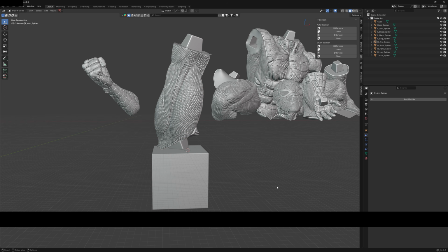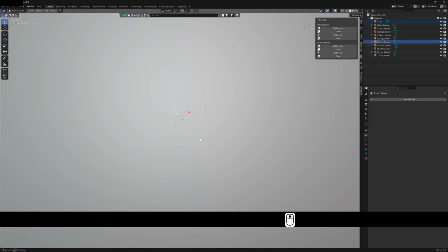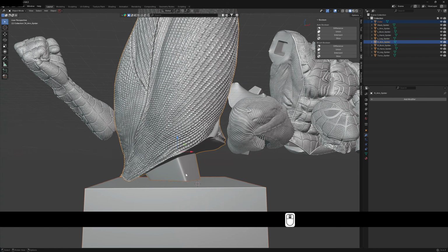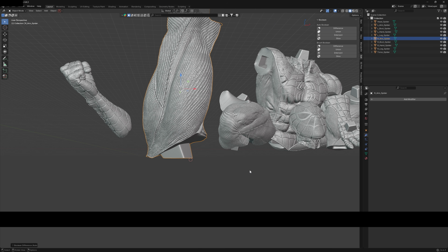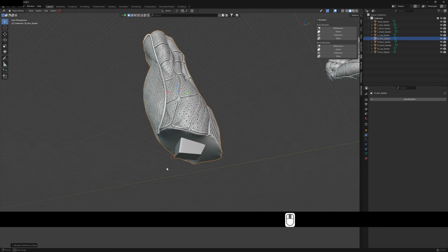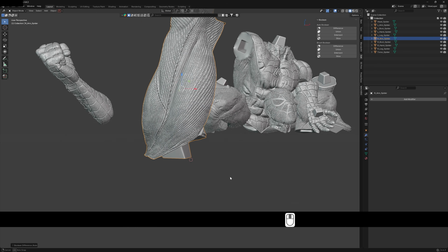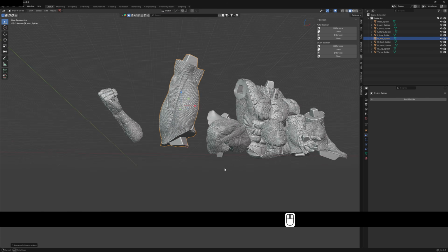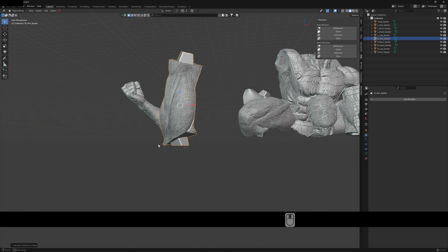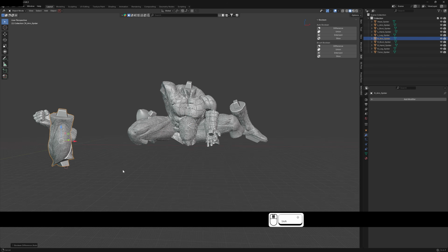So what you want to do is the first object you select is the cutter. The second object is the thing to be cut. So I want to just simply cut off the bit that's in the cube. That easy. So you just go difference. There we go. I reckon that could print better than trying to do it on more of an angle, but you've still got the peg.